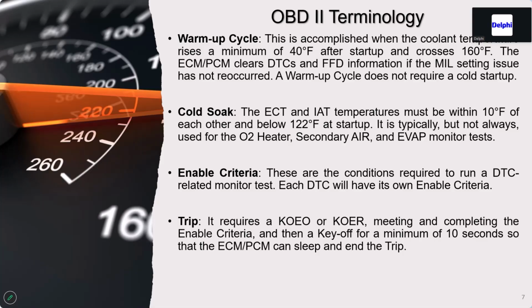It requires a key off and key on, engine off, where you might just turn it on and it might do a TPS circuit check. It might do a coolant sensor check. And after a period of time, it judges if it passes or fails. But a lot of your other tests, you have to have key on engine running. You have to meet certain criteria. And once you meet that criteria, then that's considered part of a trip.